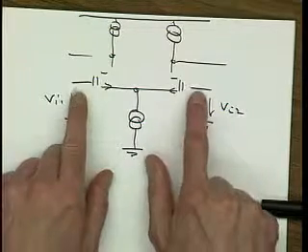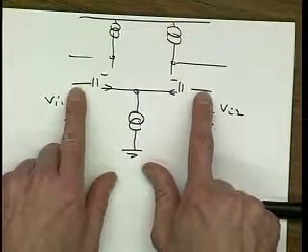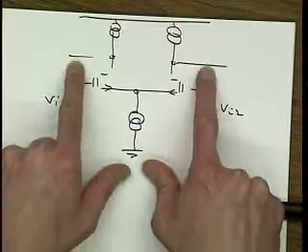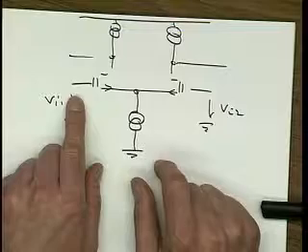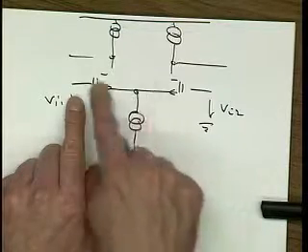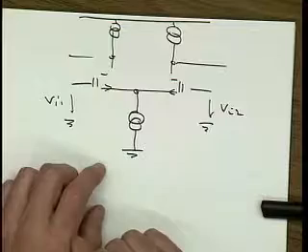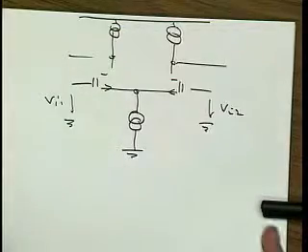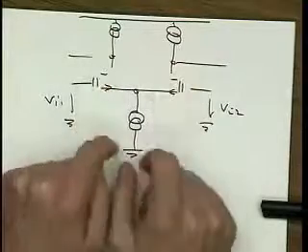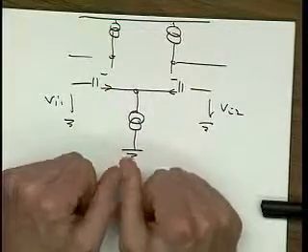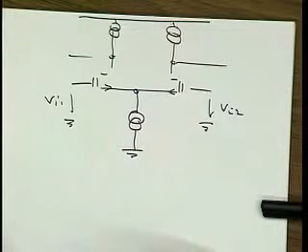This introduces then a notion of common mode voltage, and we already talked about that. If I move these terminals up and down, then at least if my amplifier is perfectly symmetrical, the current in these two branches is not going to change a whole lot if this is a good current source. And if it's symmetrical, then the small change that I'm getting is going to affect both legs similarly, and consequently I get a very good, ultimately infinite common mode rejection ratio.